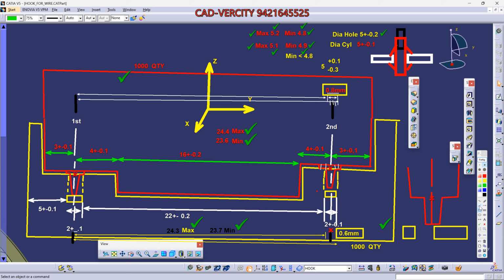So this can be the error. Are you getting it? This can be the error. Tell me, can you assemble this locator? As I mentioned, this will be your master locator. This is your master to position the red part within the yellow part. First, you will assemble this locator, then you will try to assemble this one simultaneously. So there will be a condition that this will be the overlap of 0.2. Yes or no? Yes, sir.